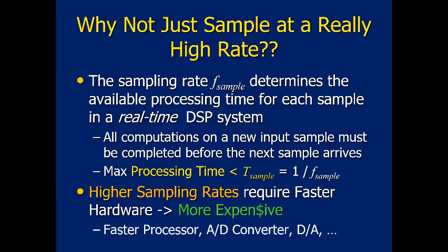So the engineering of this sampling process is usually a trade-off between choosing a high enough sampling rate, certainly first to satisfy the Nyquist criterion, at least twice the highest frequency we want to preserve in our signal, plus some amount of oversampling to minimize the possibility of aliasing, working in conjunction with an anti-aliasing filter, hopefully an affordable one, to prevent any signals that might alias from getting into my system.